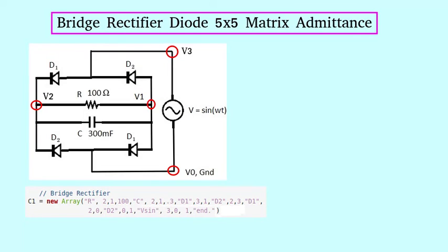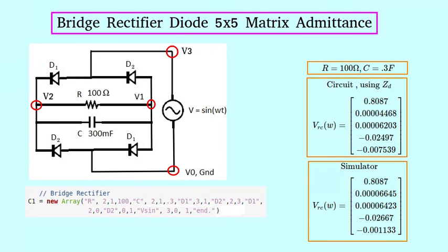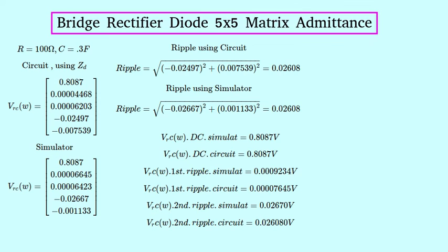So now to test these matrices, we'll insert the first model in for the diodes labelled D1 and the second model in for the diodes labelled D2. We'll write up this simple circuit file and solve using these matrices for admittances that we've defined earlier. So these are the result vectors. The first is from the circuit program and the second from the simulator, and they look very consistent. I could rewrite it up like this.